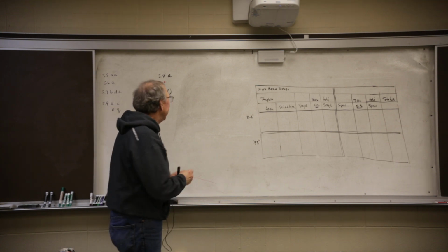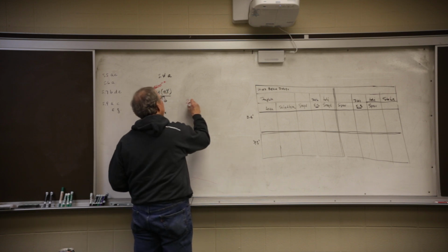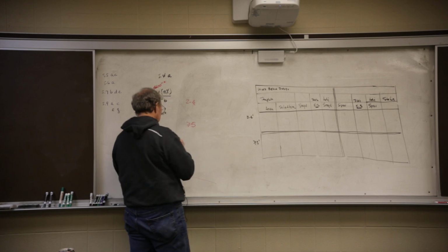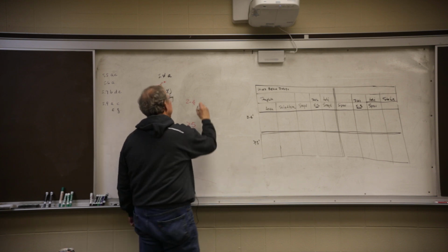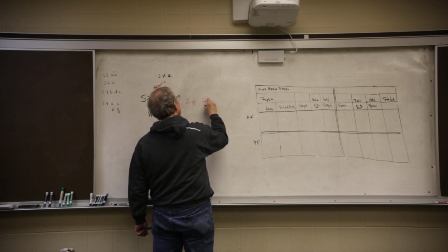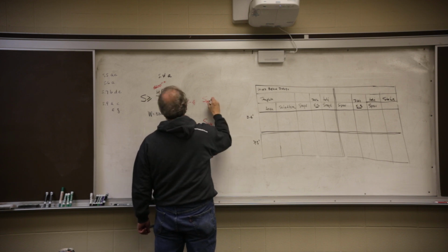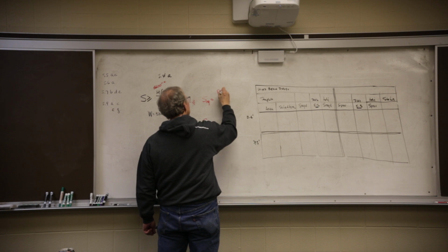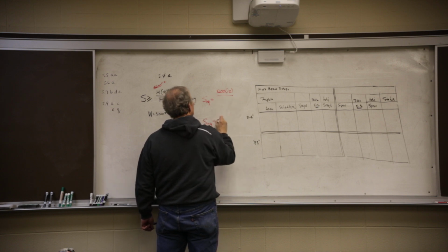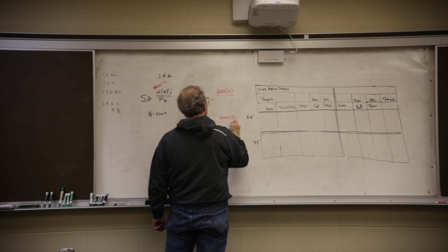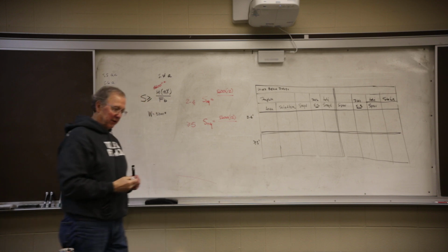I run one with 2 to 4, and I run one with greater than or equal to 5. So, S required is equal to 5,600 times 12 inches per foot divided by the stress in the table for each of the areas.